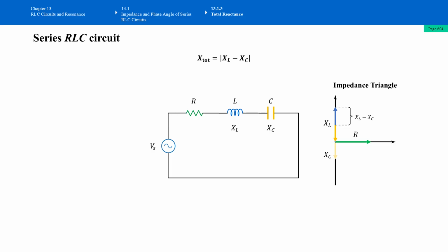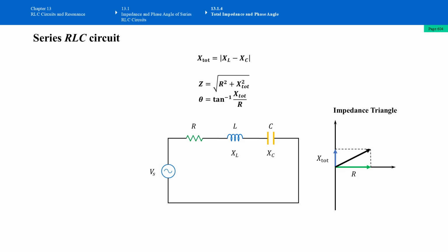And then we can use our impedance formula, the formula that we used in previous chapters for finding the total impedance of RL series circuits and also RC series circuits. Over here it is for the RLC circuit, but the same template. Take a square root of R squared plus X total squared. This formula is for the impedance of this RLC circuit.